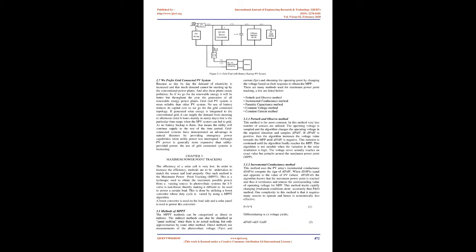2.1.2 Series and parallel connection of PV cells. Solar cells can be thought of as solar batteries. If solar cells are connected in series, then the current stays the same and the voltage increases. Figure 2.5, Series connection of cells. If solar cells are connected in parallel, the voltage stays the same, but the current increases. Figure 2.6, Parallel connection of cells. As we know, those solar cells are combined to form a module to obtain the voltage and current, and therefore power, desired.